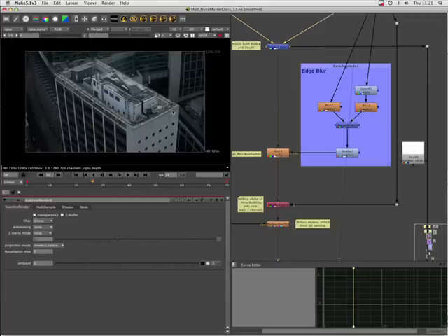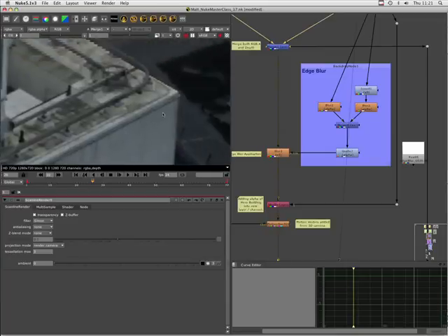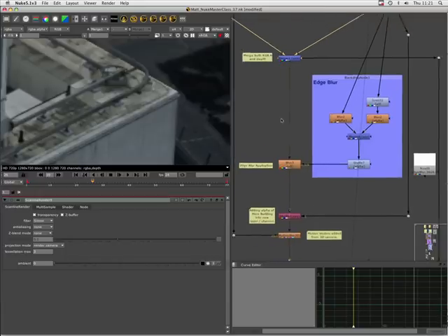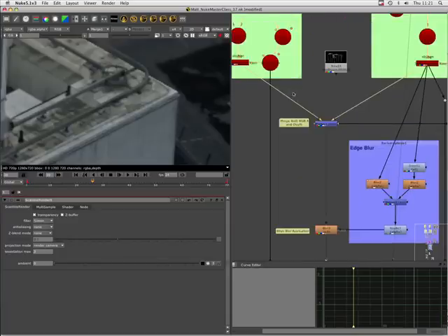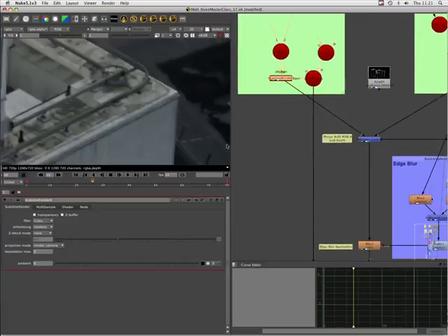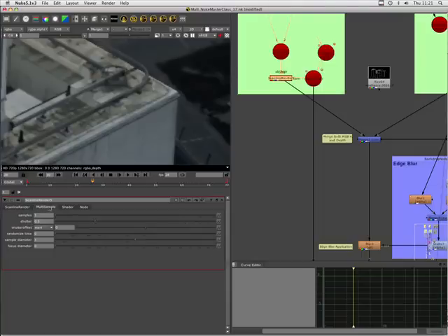Now, one of the things I wanted to do was just deal with these edges where we're getting some pixelation. I've put this on deliberately so I can show you this technique. I'm sure you're aware of it. The scanline renderer has the ability to have anti-aliasing added. I've just got it on quite a low setting here. If you go into the multi-samples, you can really crank this right up.